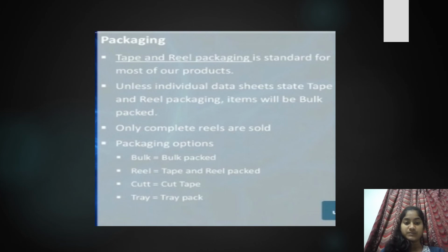Supply current, phase noise, output configuration and drive capability. Different VCXOs have different output circuit configurations. It is important to check that the output will satisfactorily interface with other elements of the electronic design: impedance, capacitance, drive capability, configuration, and the like.